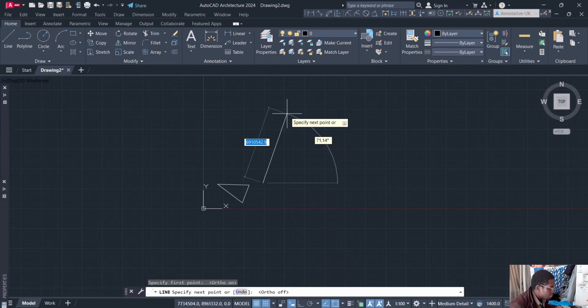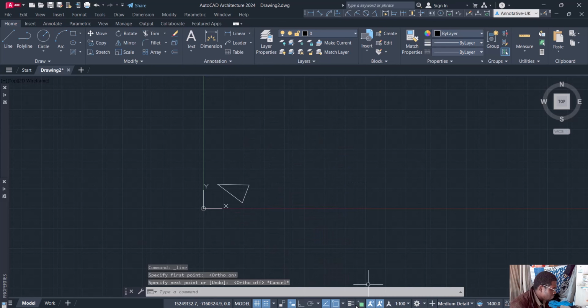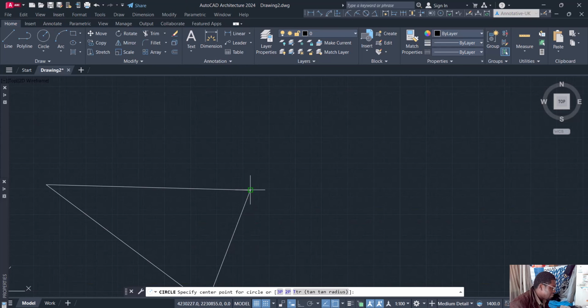The next thing is, you can see here there's something we call snap cursor, object snap. This object snap is very important. If I want to draw a circle, and here you see when I bring the cursor to the edge, the meeting or the end point of the angle, you see that it has been snapped.